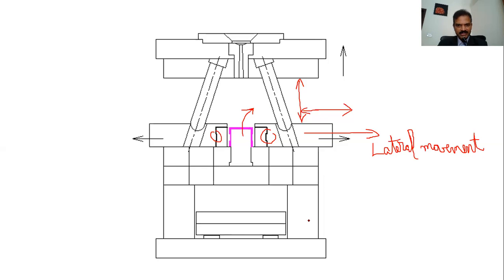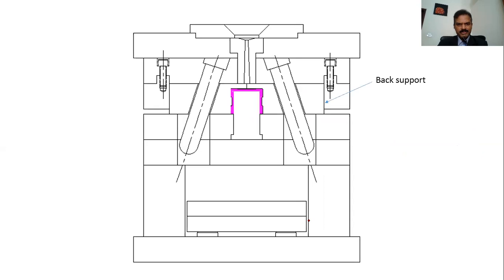What I mean to say is, see, these fingers are only meant to bring the slides in and to take the slide out when it moves in and up, right? You see the clearance here, like a millimeter maybe per side.